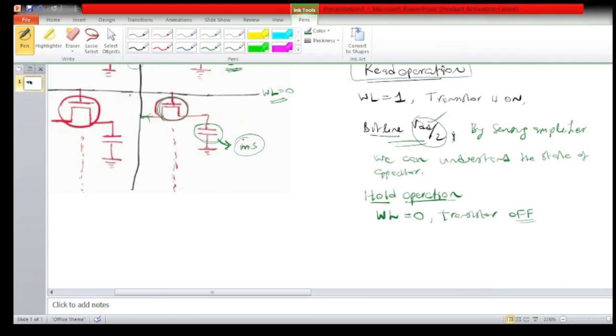There will be some counters that do all these processes, measuring with what time we have to refresh or recharge this capacitor to retain its original state. So there are some additional circuits to ensure the state of this capacitor, or the charge inside it. After every few milliseconds, we have to recharge this capacitor.